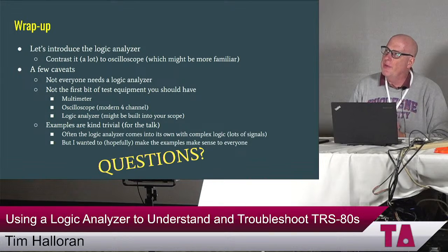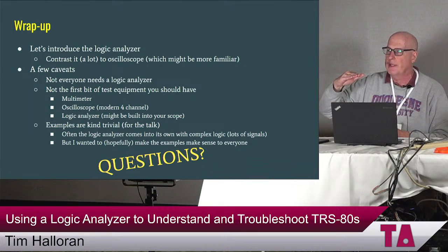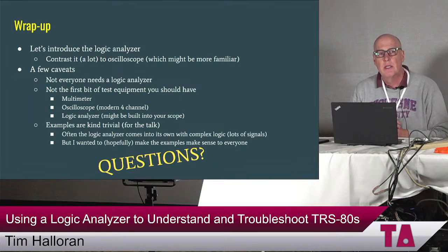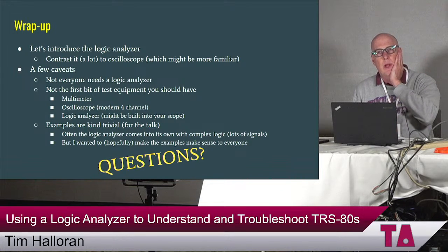However, I don't think the sampling rate is the issue. Like I said, I've run into far more problems with making sure you have the voltage set right, because a lot of these things assume you're using CMOS circuits, so we're oftentimes touching TTL, so you want that voltage a little bit lower, that voltage divide, and you want to make sure you can change that. That's where I've run into problems. The sampling rate has been less of one. Although I will mention one case where I did run into that.